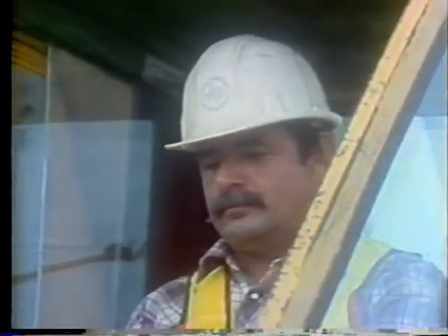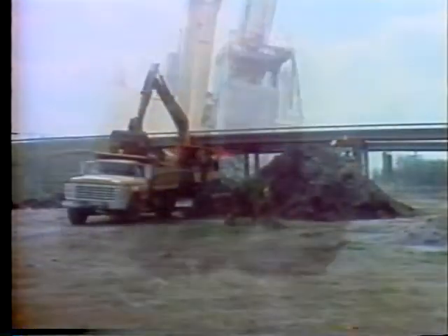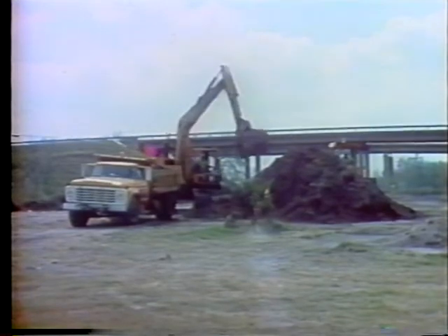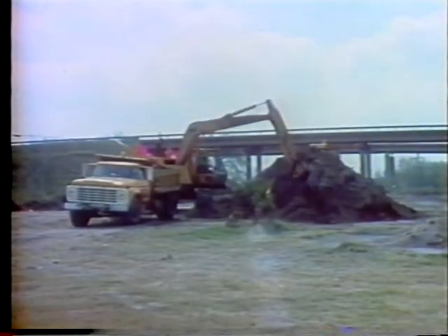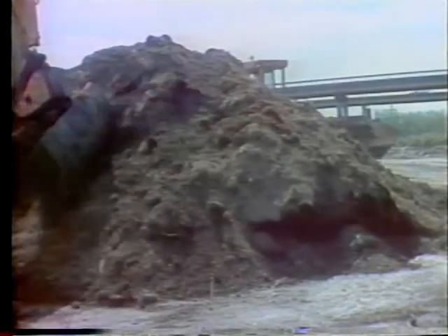Excess material should always be used to flatten slopes and ditches to make them safer and to eliminate the need for a guardrail. A log should be maintained of potential waste and borrow areas along a given corridor that can be used for this type of work.